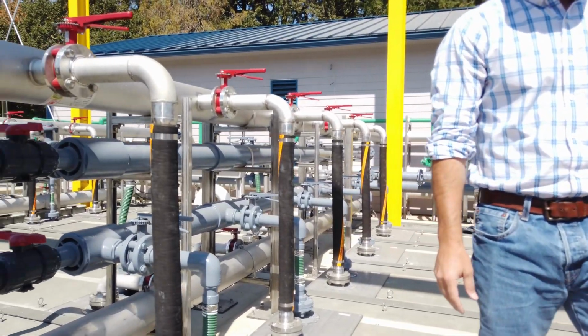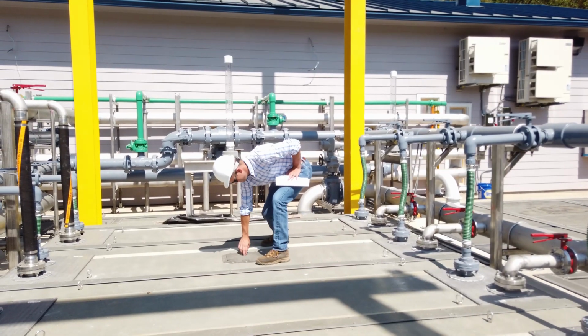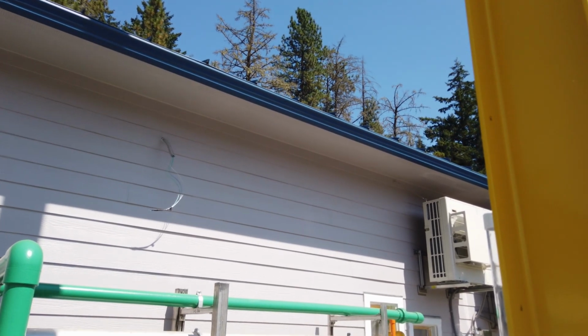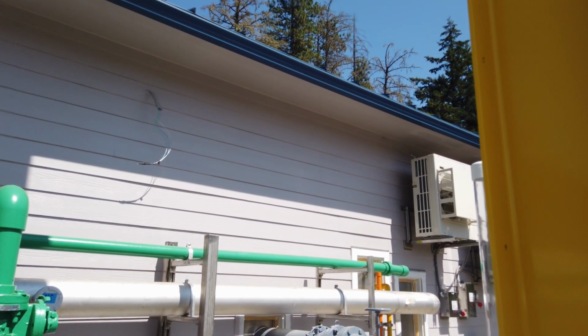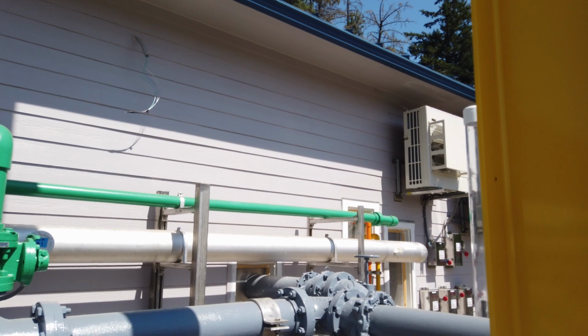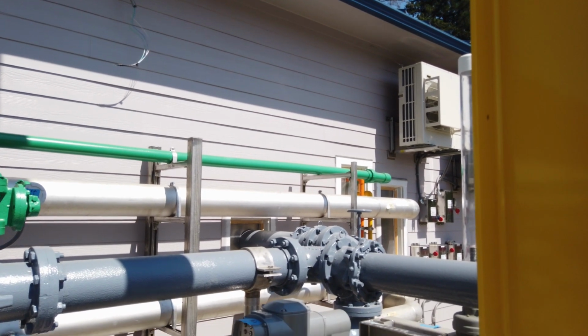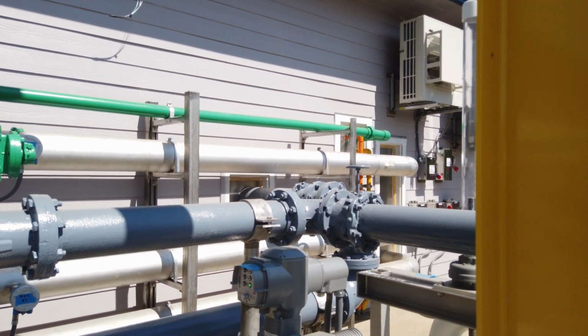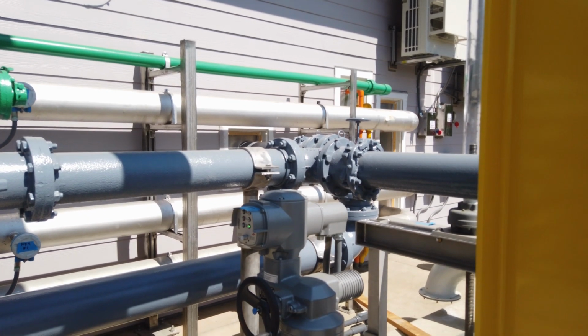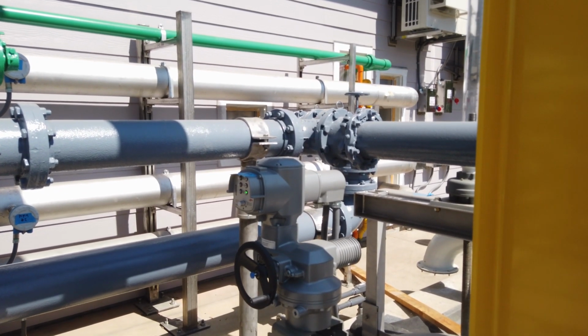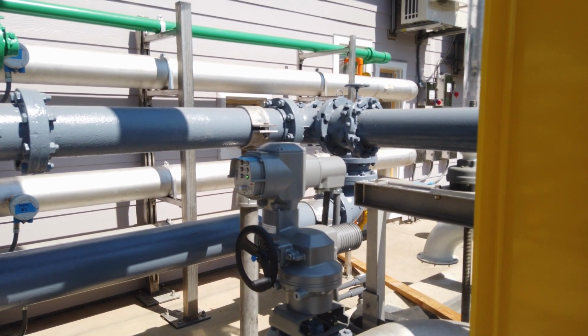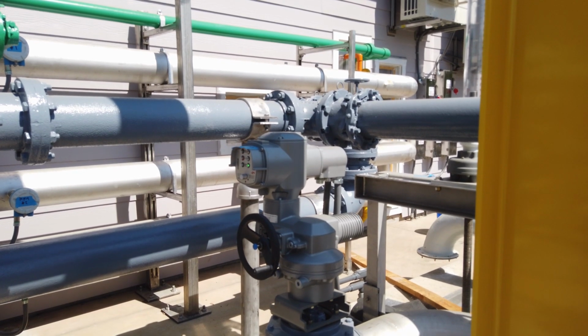You will notice stainless steel air piping on both sides of the tank. Once a day, the coarse bubble diffusers are cleaned by opening an electronically actuated valve that pulls mixed liquor into the air piping and returns it to the distribution channel. This effectively scours the coarse bubble orifices to keep good airflow and membrane cleaning.